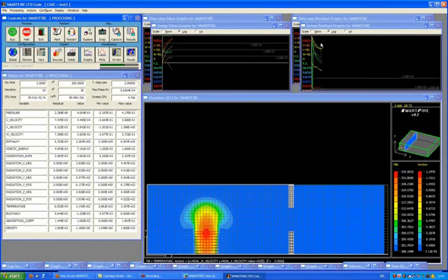Convergence is determined by considering the residual values in the status window or in the trends of the graphs in the sweep residual. Ideally, towards the end of a time step, you'd hope that these values are tending downwards, although they won't necessarily reach the bottom of the graph, and you would hope to see acceptable levels of convergence in the residual boxes on the status window.